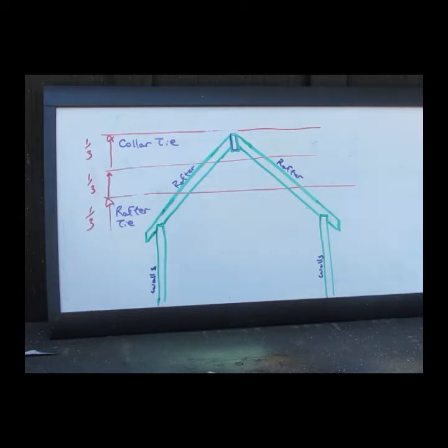So what we're doing here is not prefabbing all of our rafters or all of our trusses. What we're doing is we're building rafters in place. And the way that would work is you get a center beam and you put that in place and support it on the left and right, on the front and back end of the structure, supported up on top of the walls.